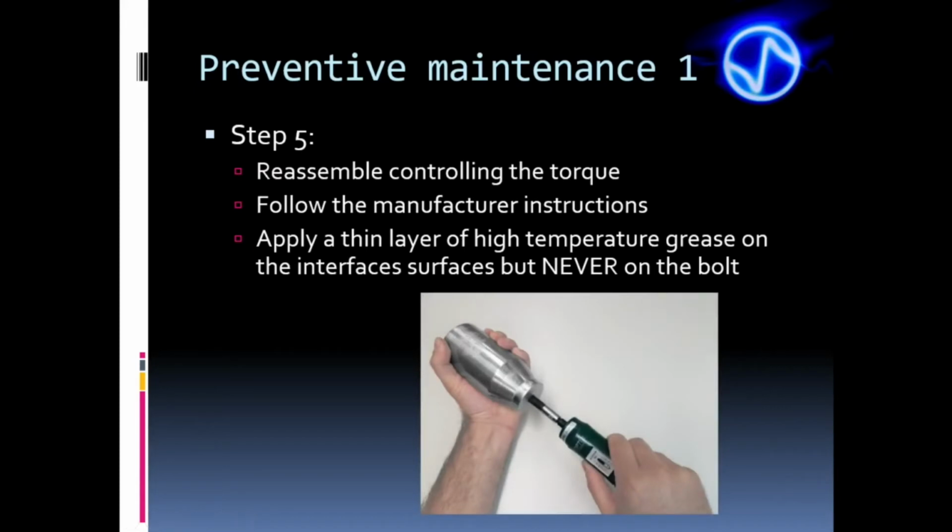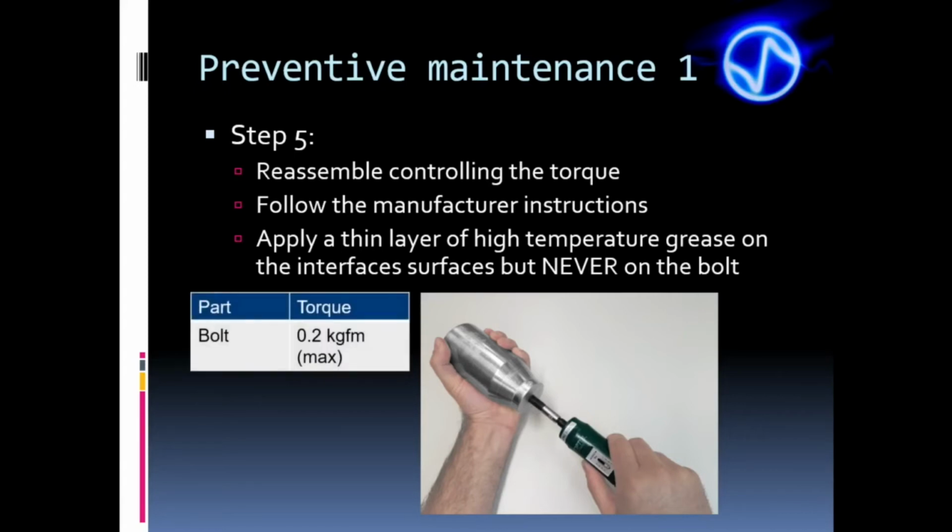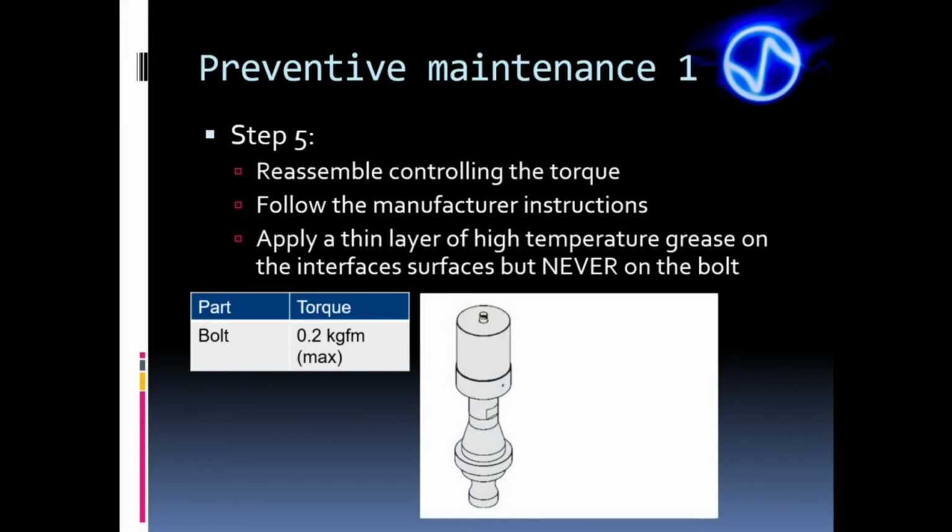Secondly, insert the studs into the sonotrode and booster, then apply a torque of a maximum of 20 Nm as recommended in this table. Thirdly, mount the converter on the booster and then connect the converter plus booster to the sonotrode or horn, always taking great care to not scratch or dent the element surfaces.